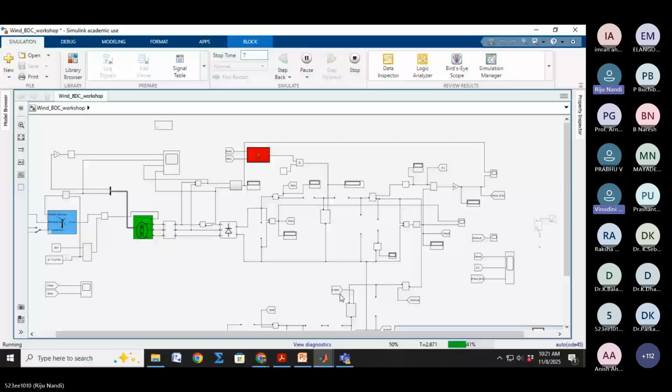Sir, for any converter, we write KCL, KVL, we know the modes of operation, then we write it and we find the ABCD matrix, right? Then in the steady state, we just check the controllability. If the rank is equal to n by n, then we can say it is controllable. Then can we find the transfer function from that ABCD? Is small signal modeling required or not?